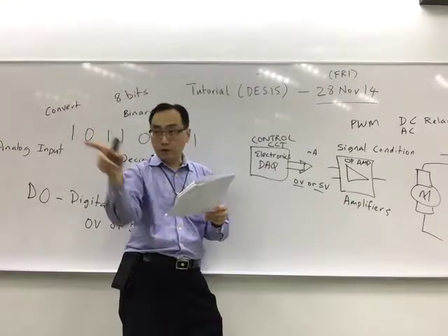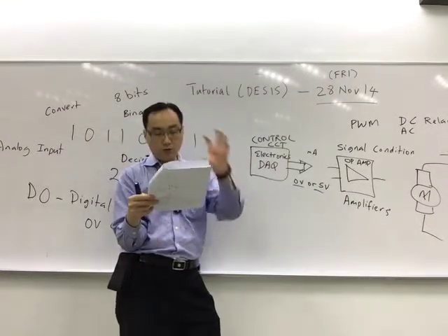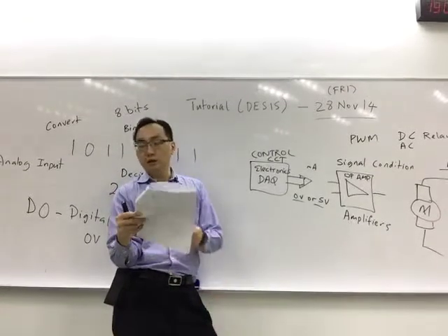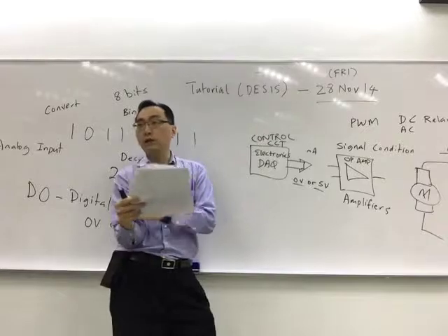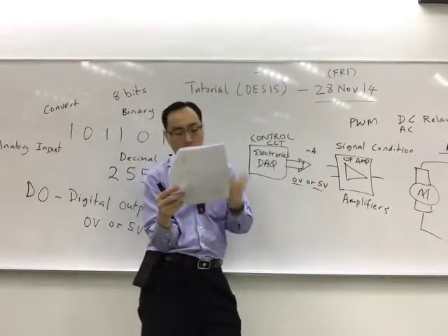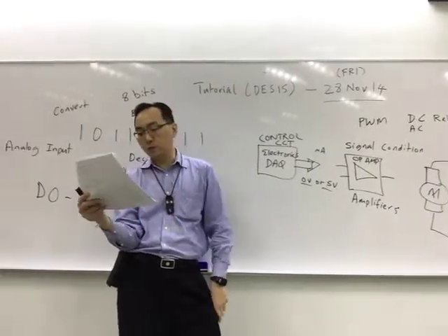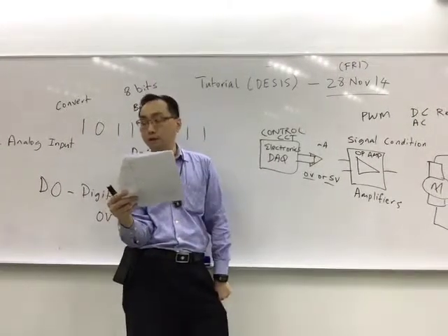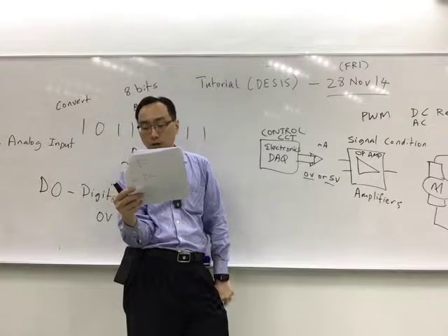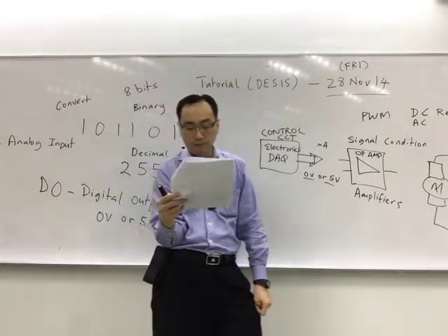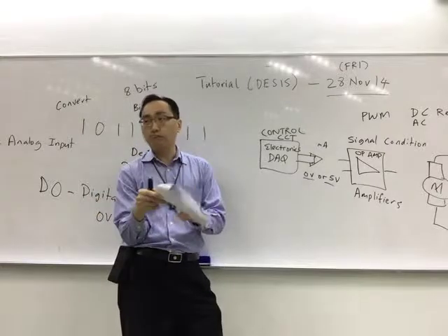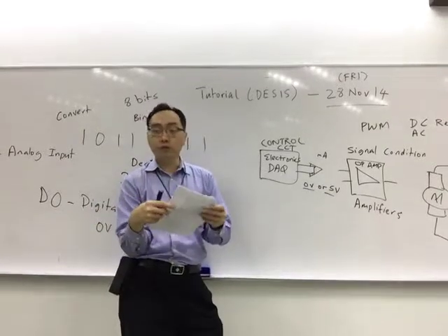So for the case of the question, your DAQ card cannot supply very high current, definitely. You have a maximum of 20 milliamp, so you cannot drive the valve dispenser, nor even the motor, because your motor needs very high current. It's a high load, greater than 10 ampere. Even things like the AC pump, it's not enough to drive.